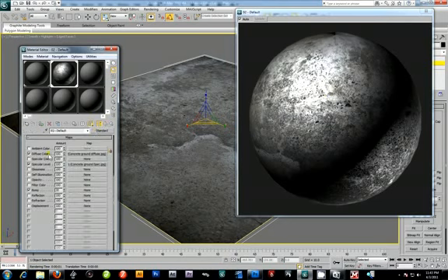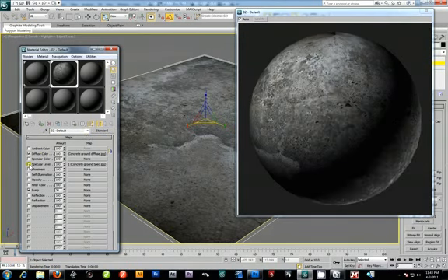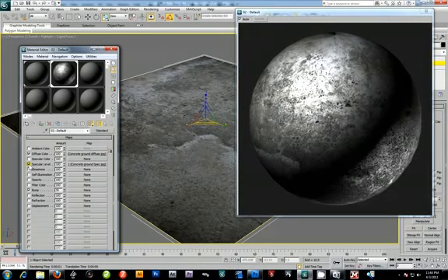Now watch when I turn that off. I went to my parent level and I'm going to turn off the check mark. It lets you know that you're turning off the map. There, specular off, specular on. But notice it's taking a while to load because those are huge maps. What you could normally do is, once you've got them in there, resize them and then save them over, and they should update.